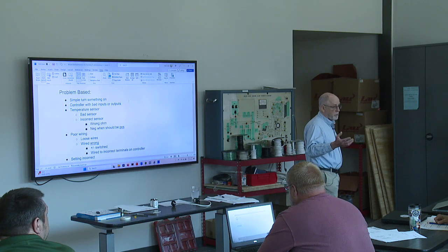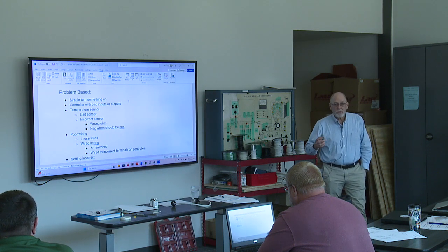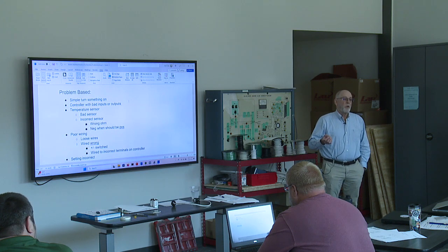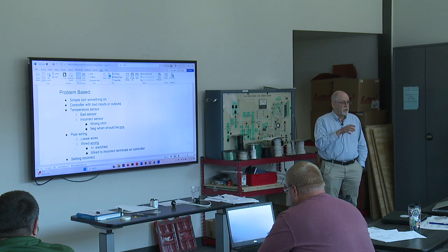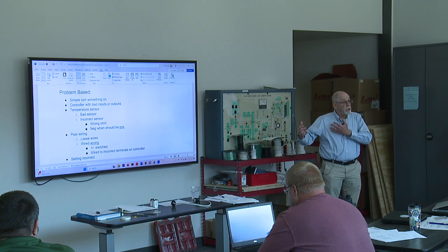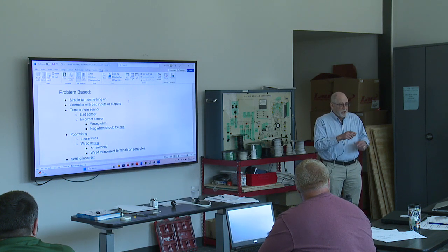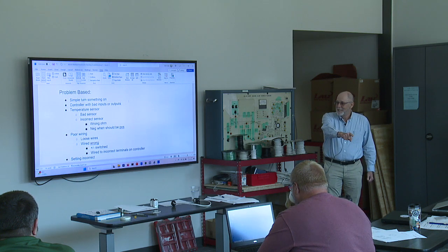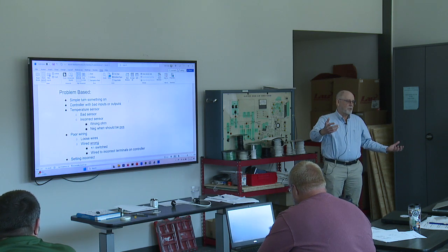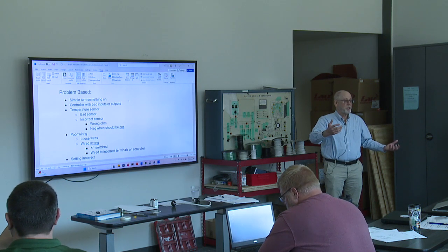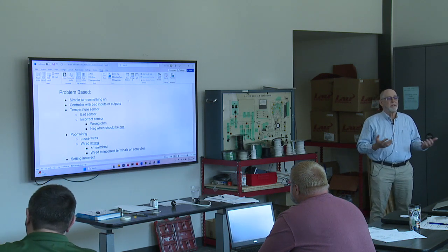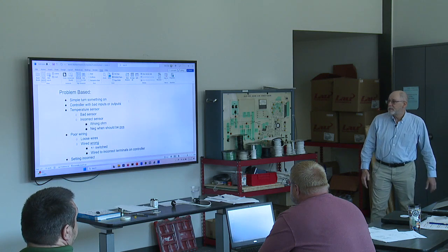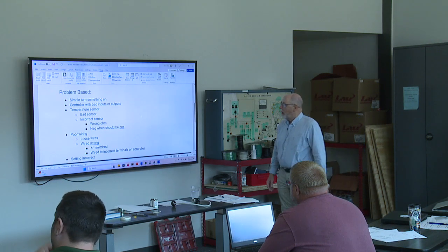And then because it was wintertime, by the time noon came around, it was 80 degrees in her room. So I went to where the guy was in the closet for Johnson Controls, working on the computer there, and I said, this is what's happening in that room. Check on it for me. Well, that's not right. My computer says it's 72 degrees in that room. Well, short story, they had the wrong sensor wired up for that room in the controller, right? So they were seeing incorrect and controlling off the incorrect temperature in the space. So those types of things for troubleshooting.